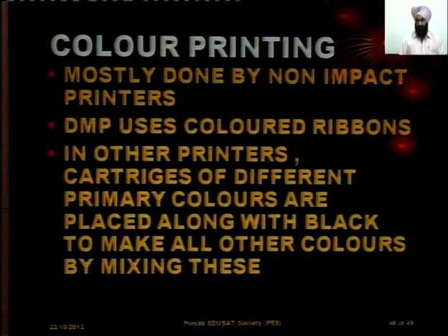So, today in this discussion, I have tried to discuss the definition of printer, then different kinds of printers, different categories of printers, and the construction and working of dot matrix printer, inkjet printer and laser printer, and I have also touched on color printing in this lecture.